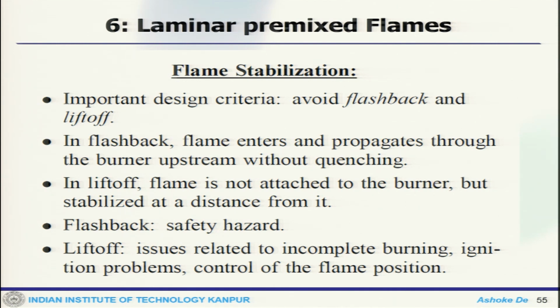Why do we talk about flame stabilization? Because this is a very specific and important issue for premix flame, because we have already seen how premix flame is susceptible to issues like extinction, flashback, lift off. It is quite necessary to understand flame stabilization to avoid flashback or lift off, because these affect the design of your reacting system.